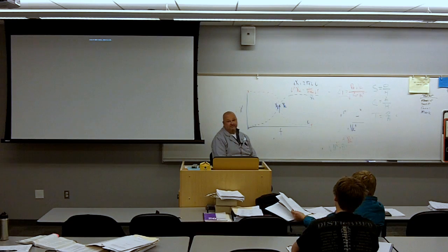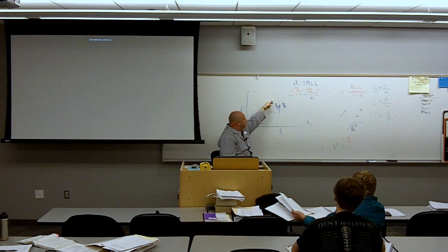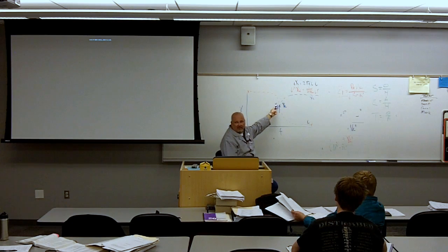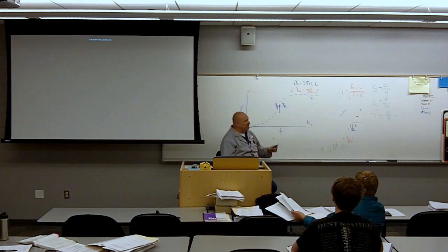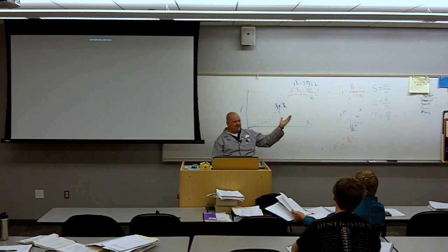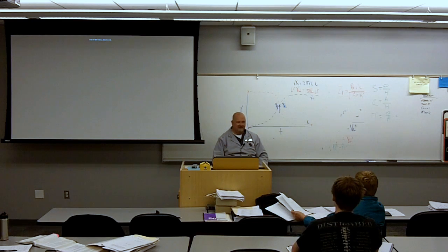You're looking at the answer. If I'm below resonant frequency, what kind of a circuit am I dealing with predominantly? Capacitive circuit. If I'm above resonant frequency, what's the predominant value that I'm going to be dealing with? Inductive. The blue cancels out the red, the blue wins, if I'm above resonant frequency. If I'm below resonant frequency, the capacitor wins. So you're either going to be dealing with an X sub C circuit, an X sub L circuit, or a purely R circuit at resonance.